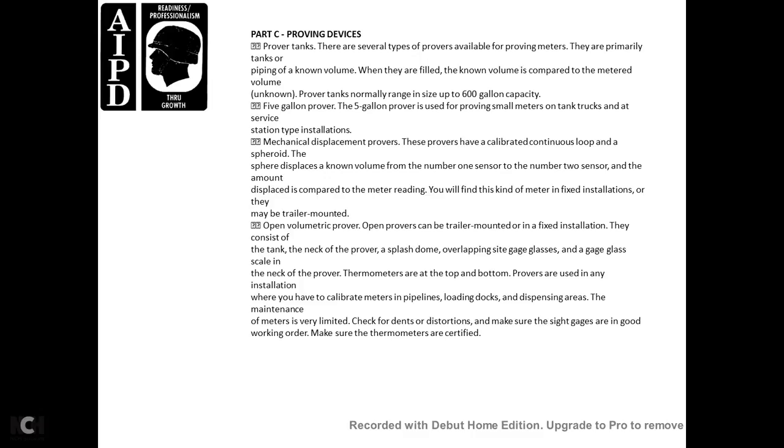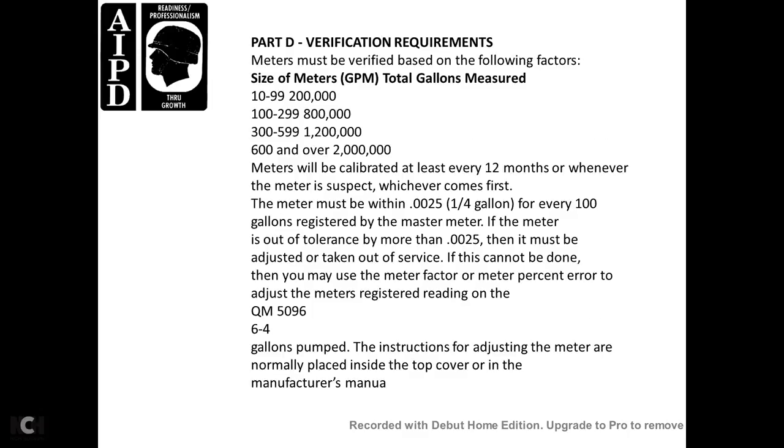Where you have a meter in the pipelines, at the loading dock or dispensing area, the maintenance of the meters is very limited. Check for tension and distortion, make sure the sight gauges are in good working order, and make sure the thermometer is certified.